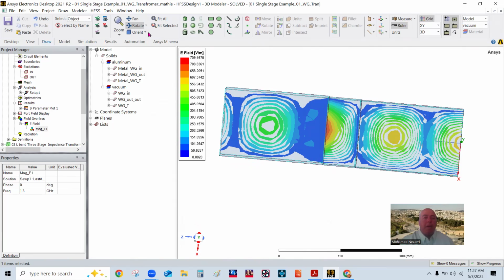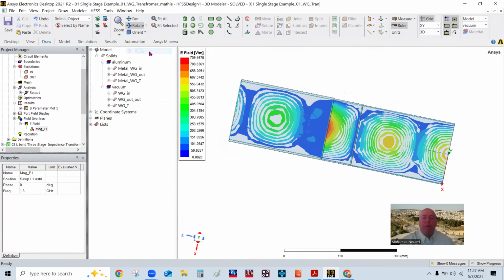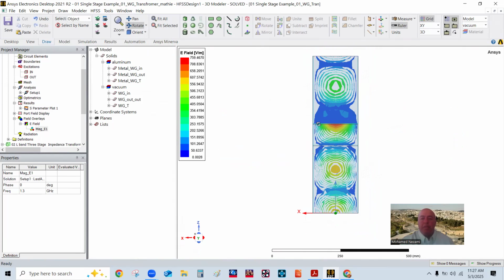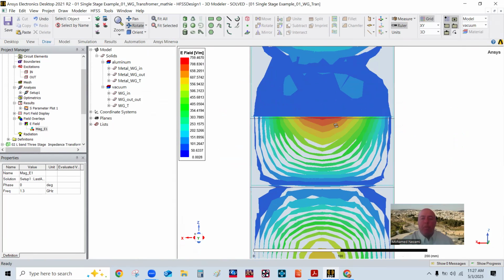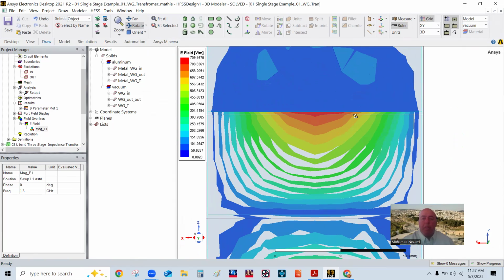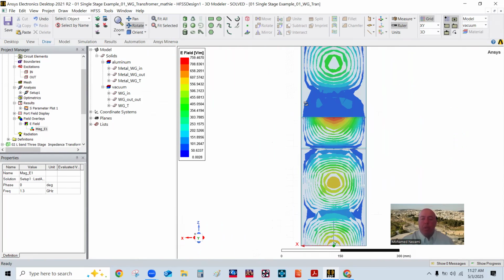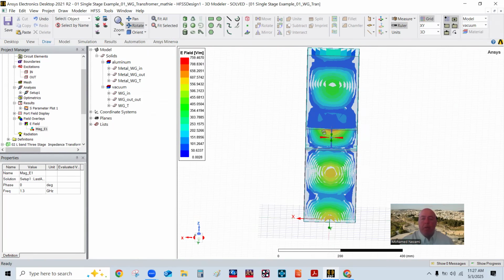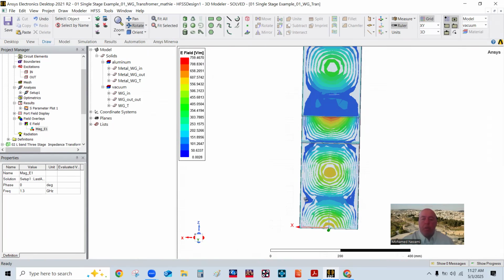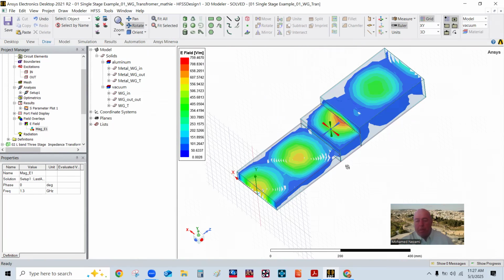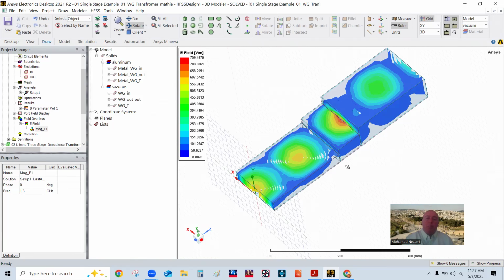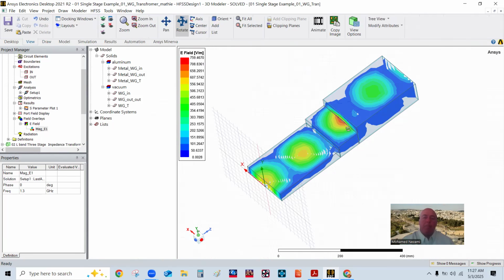You can see that really clearly by viewing this. If it was really a quarter wavelength, this would have to be sitting right in the middle of one of these, because as you can see from the pattern, each one of these repeating patterns from here to here is a half wavelength. And from the null to the middle of this is a quarter wavelength. You remember that from the fundamentals of propagation in waveguides.